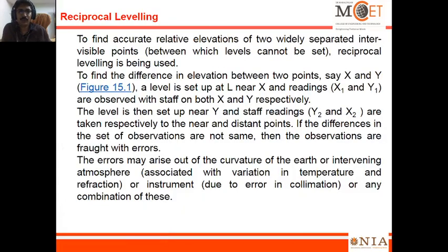To find accurate relative elevation of two widely separated intervisible points. The points are visible, but we can't keep the level. We can't set the level. That is the reciprocal leveling.